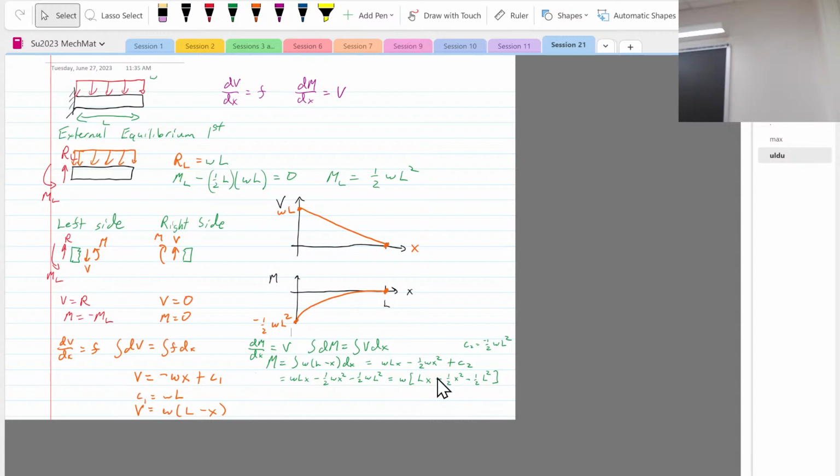My hang up right now is associating the different loadings with x, y, z for the Mohr circle. So what you have to do is go through all that. You probably won't have these diagrams directly, and you probably won't have a problem like that. We're typically dealing with 2.5D problems, so you'll have a sigma x, a sigma y, and a tau xy, or a sigma y, a sigma z, and a tau yz. We're drawing a planar diagram for in-plane stresses, then we go about doing Mohr circle.